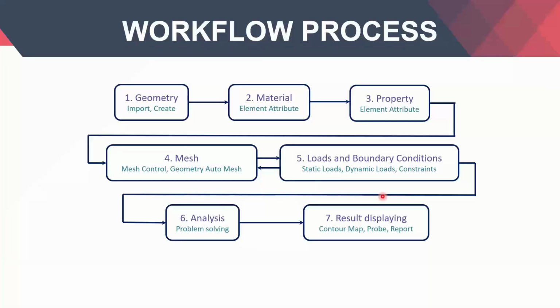So at first we'll start with the workflow process. Some of you might be new to numerical modeling. So in the workflow process, you have to first start with the geometry. Either you can create your geometry ground up, but I will recommend if you have the CAD file from your drafting team, just import that. There is no need to develop a geometry ground up that has already been developed in a different software.